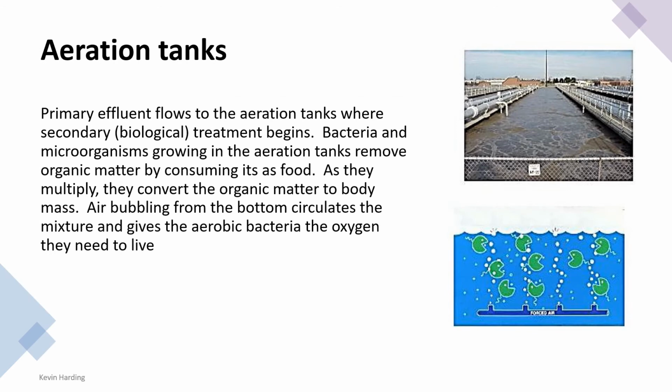So those aeration tanks, just looking at it slightly differently, so we will have air coming. This is a terrible picture quality rather. So there's a pipe at the bottom of this tank, like we've got in the top and in the previous slide. There's this pipe at the bottom where we force air through it. It then bubbles up through here, which allows for mixing as well as for the microorganisms represented here as little green Pac-Man type things, which then eat the organic matter. They can then eat any of that organic matter to remove the pollutants, and then it's easier to remove the microorganisms later.